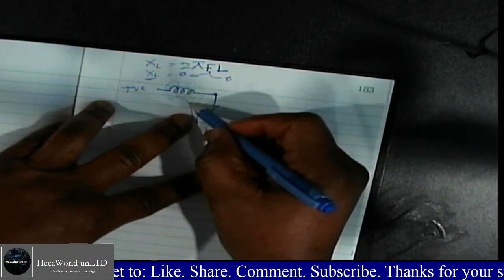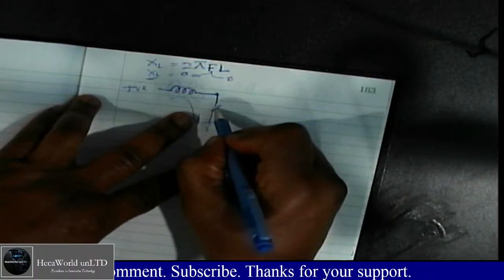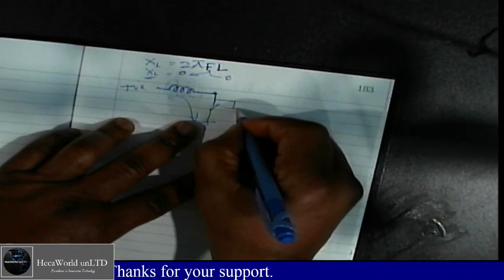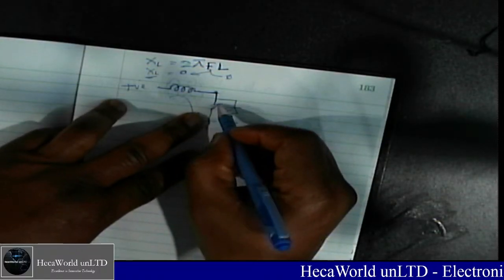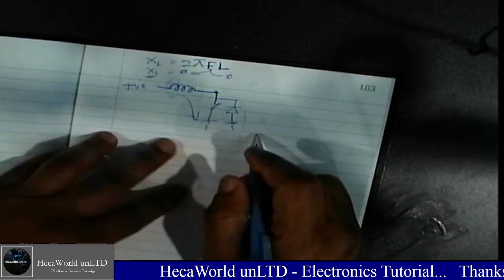That electrical energy generated could be as high as anything, as little as anything. But sometimes it could be so high that it might burn off your switch. So what we do then is put a diode across the switch to create a flyback effect, or to prevent inductive kickback. So if I have a diode like this, then when I remove this source of electricity here, instead of burning off my contacts, the current that is generated in this conductor will go through the diode and to ground.